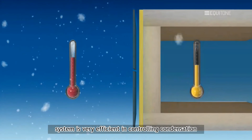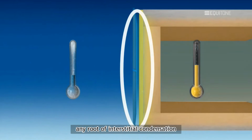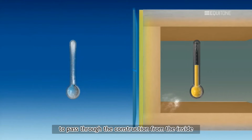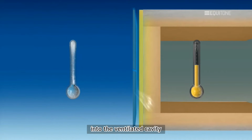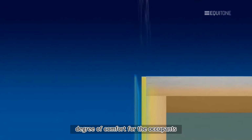The rain screen system is very efficient in controlling condensation. Any risk of interstitial condensation occurs in the ventilated cavity. The breathable structure allows water vapour to pass through the construction from the inside into the ventilated cavity. All of this results in a greater degree of comfort for the occupants and ensures a healthy building.